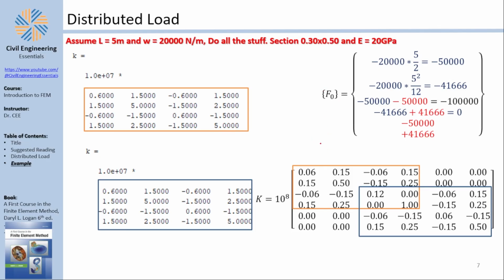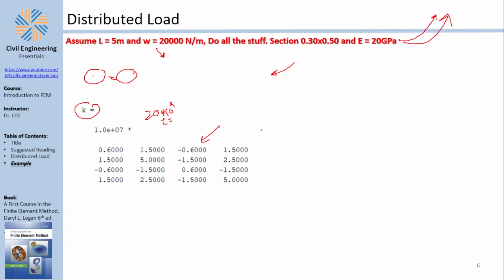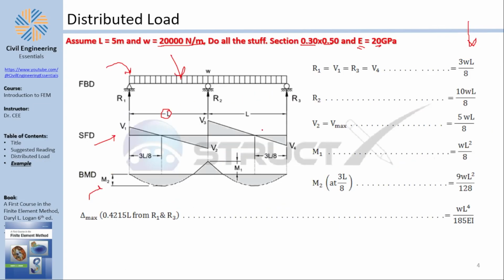Of course, we are pros, and I just did it quickly. But doctor, where is the transformation matrix? I remember you saying something like T transpose K T. Where is this stuff? It's not here today because our beams coincide, luckily for us. So far, our beams' local axes coincide with the global axes of the entire structure, and that's the reason why no transformation occurs.